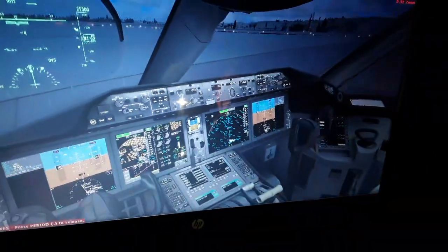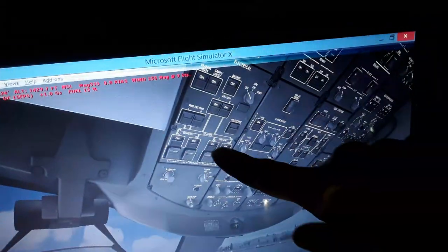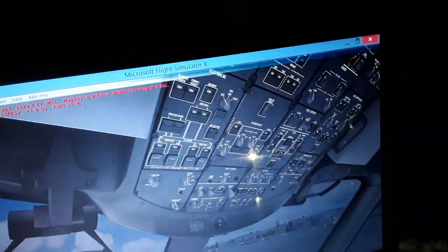We'll make an engine start demonstration. Also now the overhead panel, the electrical. I will need to start the APU to make an engine start demonstration. The APU is going to provide us with electric power, alternating current, 120 to 200 volts, 400 Hz frequency, and also 120 kilowatts, and also maybe less than that because we have the IDGs for that from the engines, 130 kilowatts probably. Left and right engine, the APU.